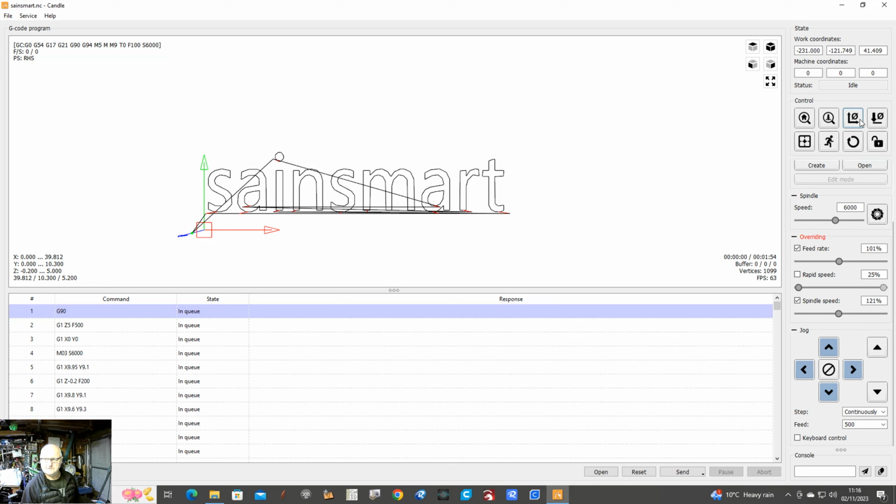Okay, that's showing you some coordinates up there. This is where we would zero then, right? So that's zeroed the work coordinates. Now I believe they're stored in an INI file somewhere, so even when you switch off or go back onto the machine again, those coordinates come up. So if anything happens, those coordinates are stored. I've never put it to the test because I've had no need to.